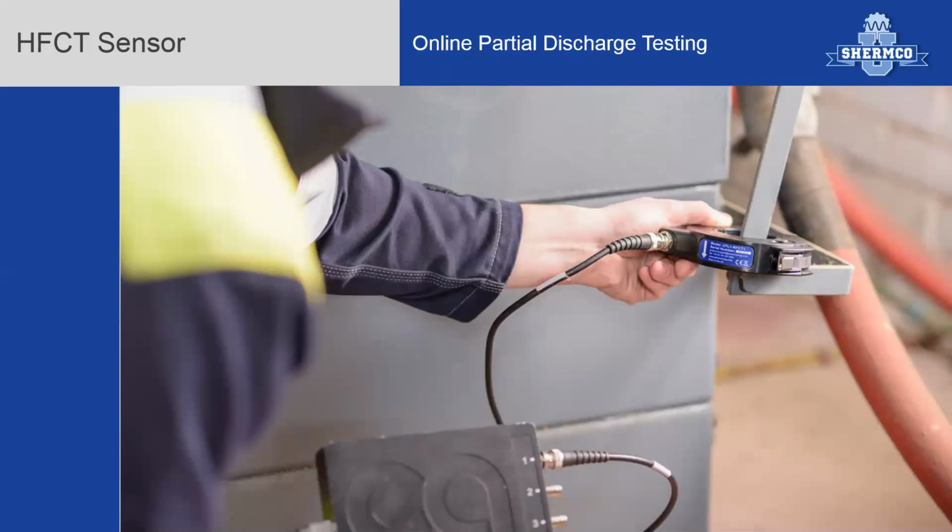High-frequency current transformers or transducers typically operate in a bandwidth somewhere around 500 kilohertz out to about 50 megahertz. Again, it may vary from manufacturer to manufacturer, but that's kind of the general range. When partial discharge occurs, there are small current pulses that are induced onto the ground shield or case ground. These pulses will travel dozens of yards or meters along the ground grid in the form of high frequency current pulses in the frequency range, as I mentioned, about 500 kilohertz out to about 50 megahertz, with usually a center frequency in and around the 10 megahertz realm.